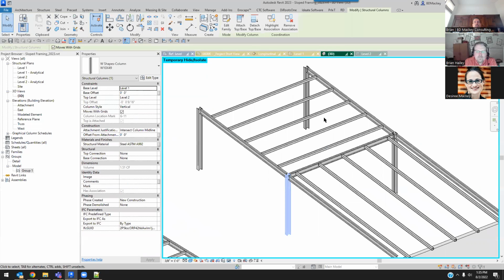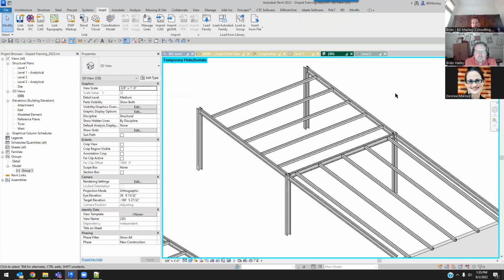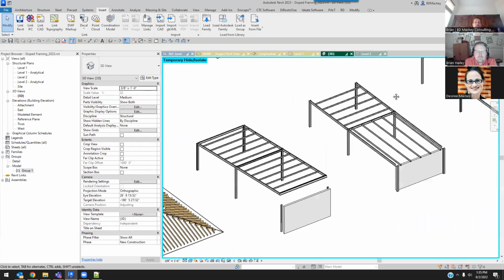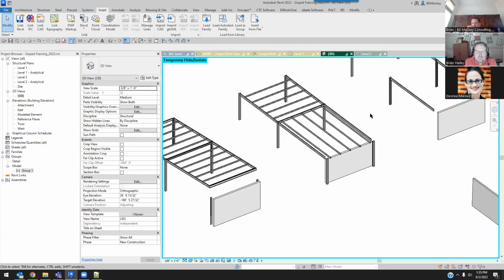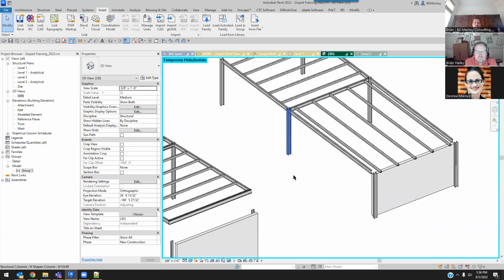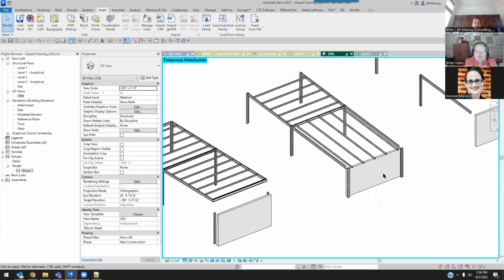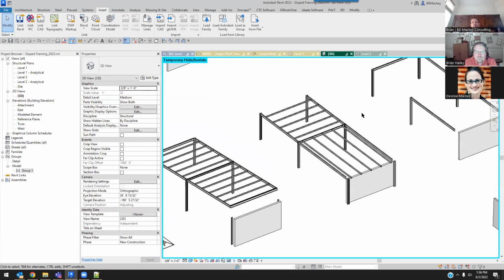So honest truth for me, I haven't been that successful doing groups in the structural world, unless it's something like, oh, I've got this column and footing and I want them to be the same, and maybe I modeled rebar or something in there. Sure, cool, go to town, bring that in as a group. But for entire bays, or in your case, you said multifamily earlier, I haven't really found it to be that useful.